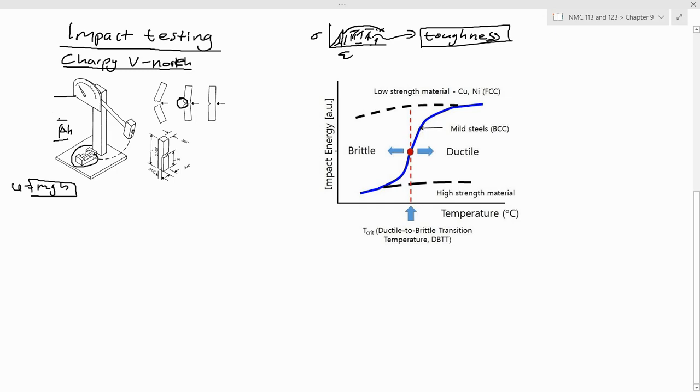The engineers did not accommodate the fact that the water may be cold. So when it hit an iceberg, that bottom part broke in a brittle manner, right? It may have been ductile at ambient temperatures, but when it goes to somewhere near 0 degrees Celsius, the material had become brittle.